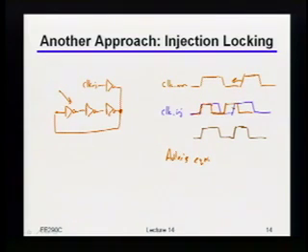Okay? Now, turns out you have to play some games to really get this to give you a full 360 degree range, because once things are pretty far apart in terms of frequency, you get into fairly non-linear mechanisms. But the good news is, indeed, you can do that. Or at least you can get about a 180 degree range. And if you can get 180 degrees, you can get the rest just by inverting the clock at your output selectively. Okay? Does this make sense to people?